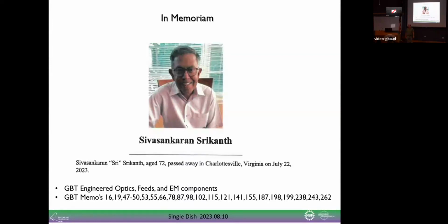And is there some gain value of the first amplifier that you should take into account for the rest of the parts? Yeah. So we usually like to hit about 35 dB gain, which is a little over a factor of 2,000. What that means is, if your next amplifier after your first amplifier has a noise temperature of 2,000, then you divide it by the gain, which is 2,000, and so that's just 1 Kelvin referred to the input. So that's kind of what we're dealing with.